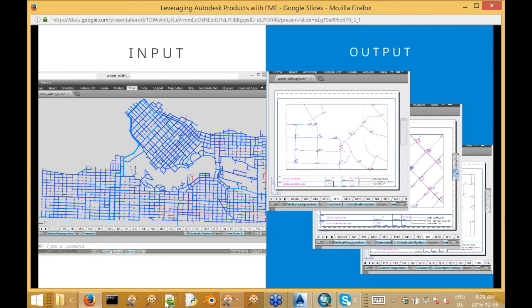They have some kind of title block with probably text added to it. In our case, the texts are City of Vancouver, date of printing, and so on. And the main part of the layout is a viewport. The layout can have one or several viewports. What is a viewport? A viewport is basically your look at your data, at your model space.